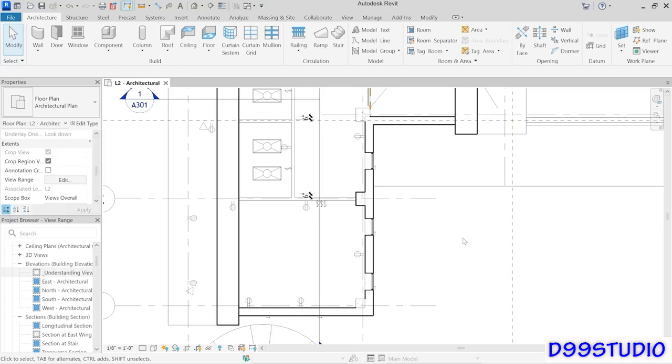However, I wouldn't call the rest of the result in the floor plan a success. You can see several things have changed, which are not desirable. We are now slicing through the roof, both over here and over here. We're now seeing lighting fixtures in our floor plan. We are cutting above the doorways here and here and these two walls. We're not seeing anything in the conference room. So clearly this cut plane is much too tall for most of the geometry in this view.